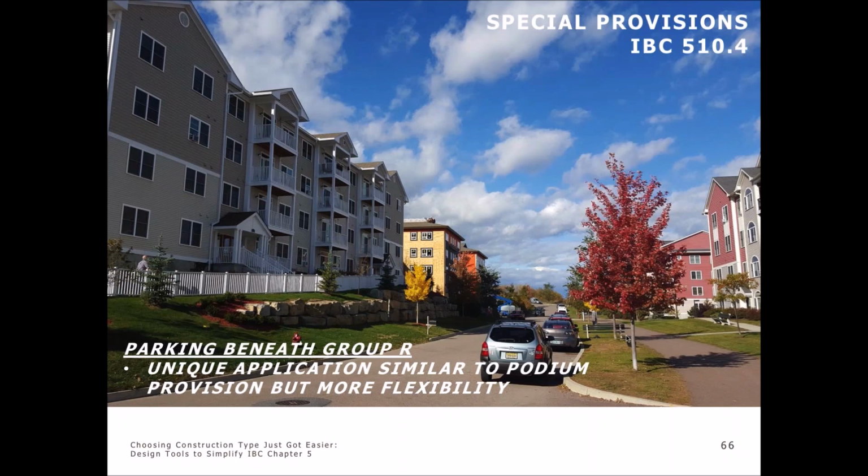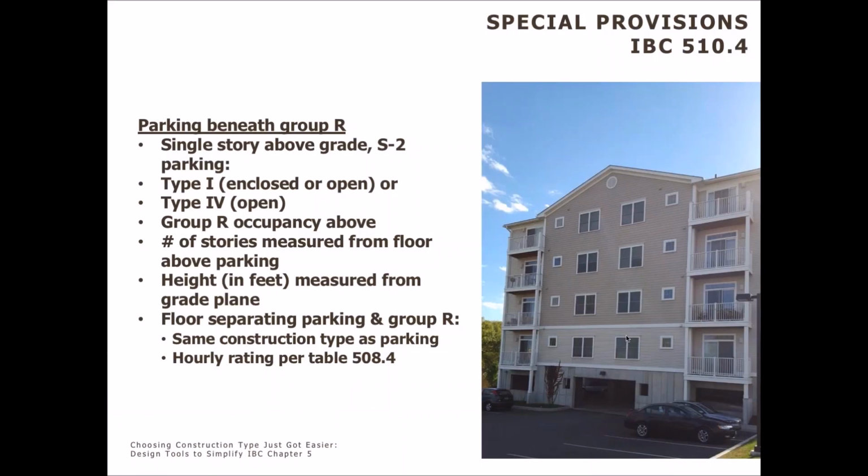One of those options is 510.4 of IBC, and this is a special provision unique to just parking that's underneath just Group R occupancies. So what the code says here is if we have just a single story from grade plane parking garage, and that's either type 1 or 4 construction, that depends on whether it's open or enclosed, and we just have Group R occupancies above, we can measure the number of stories for those Group R occupancies from the top of that parking garage level.